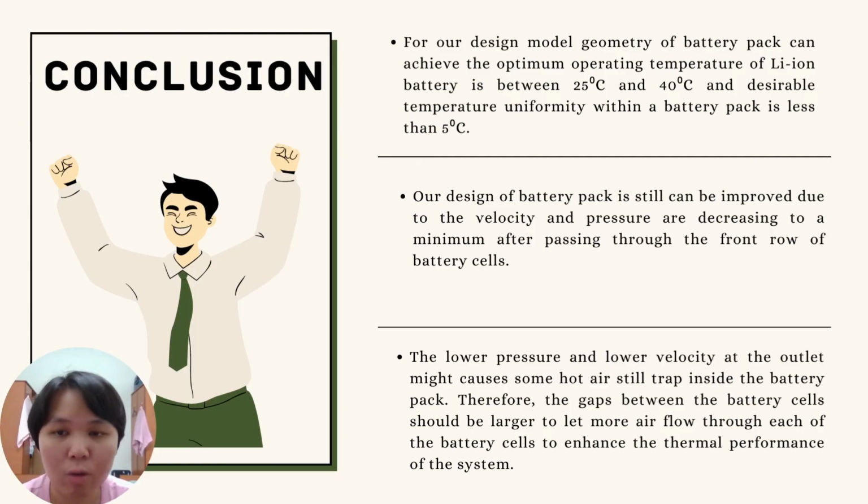And the last part of our presentation is our conclusions. Our designed model geometry of the battery pack can achieve the optimal operating temperature of the lithium-ion battery, which is between 25 degrees Celsius and 40 degrees Celsius, and the desirable temperature uniformity was also successfully obtained, in a range of less than 5 degrees Celsius.